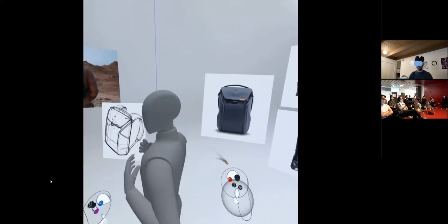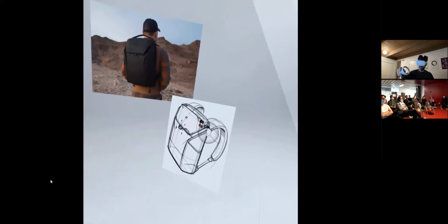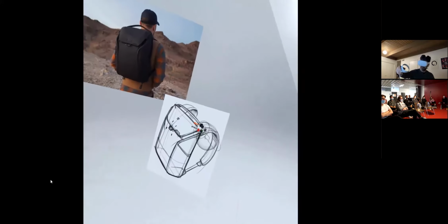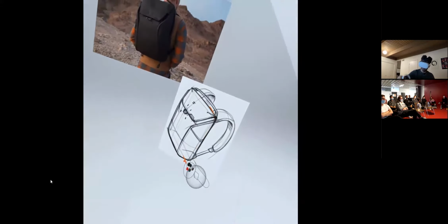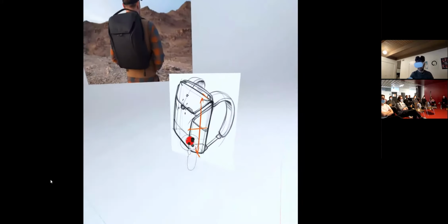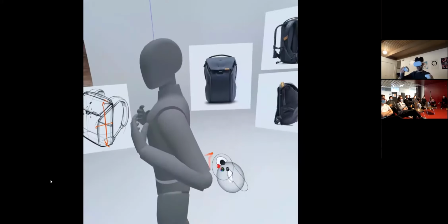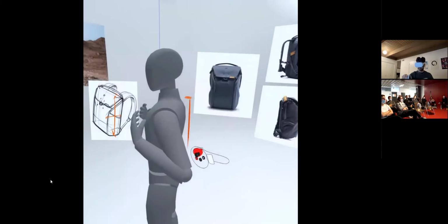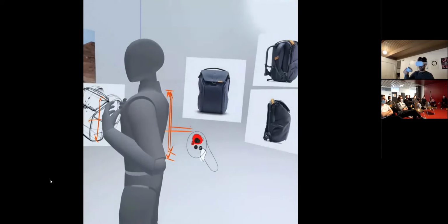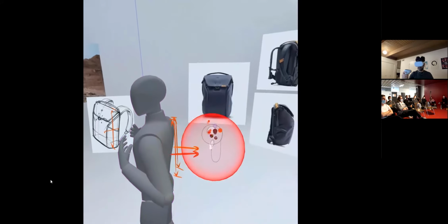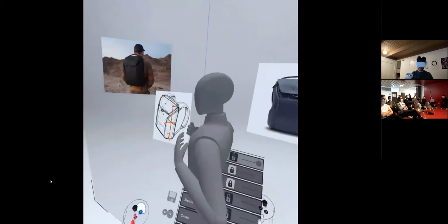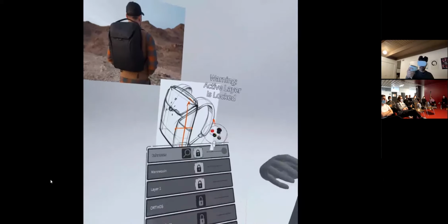So the next thing I did here is I took some measurements. I know roughly what the dimension is from the top to the bottom here. I kind of know what the dimension is, as well as the depth, so how thick that is. With those, I'm able to lay out a specific height and depth to this object as well. Now, when I have those, I'll just delete this, lock everything.